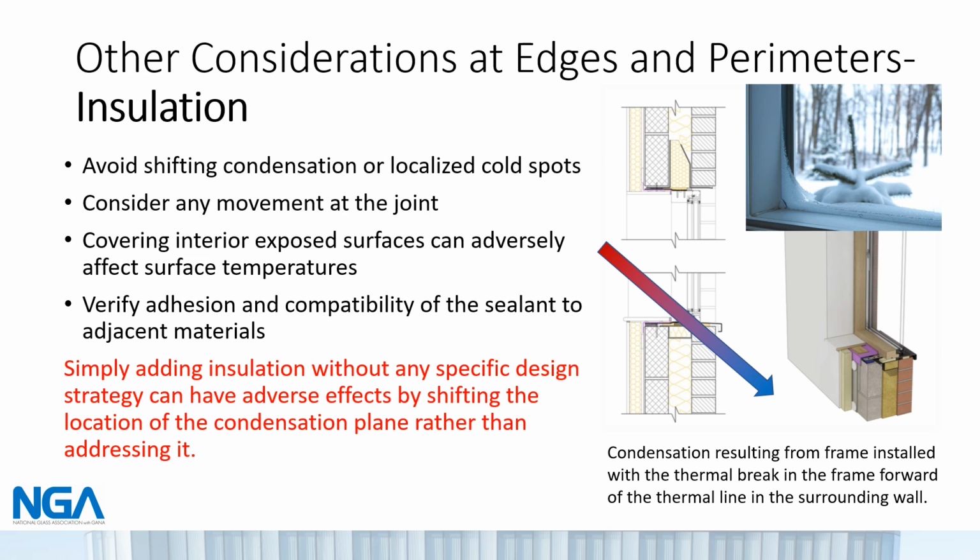The designer must be aware of the importance of maintaining a high level of thermal continuity in the detailing of perimeter conditions and how they may possibly interfere with other functions of the glazing system. For example, a design incorporates windows where the plane of glass varies significantly with the exterior face of the surrounding construction. For instance, it could be shallow at 1 inch to 6 inch offset or deep with 6 inch to 12 inch offset or more.